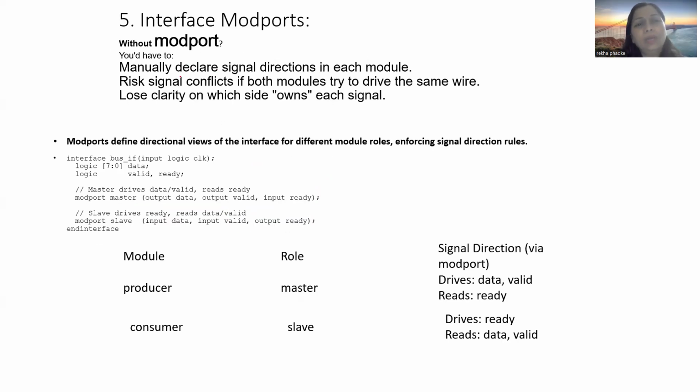So now what are mod ports? Now interface we discussed. Interface is nothing but whenever I want the entire port list to be bundled together, and the entire bundle is reused in each of the modules just by calling the interface. That's the method. That's very easy to access the ports. So one more use which you can do with interfaces is by making them mod ports.